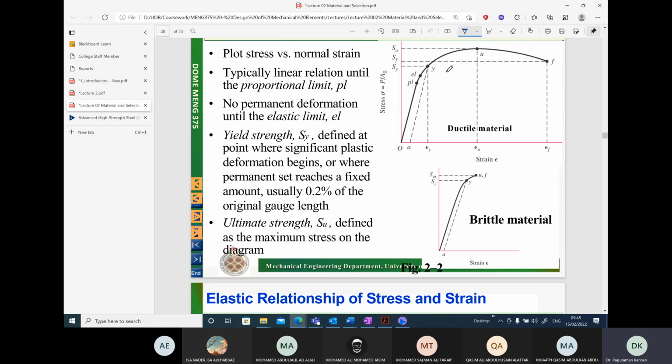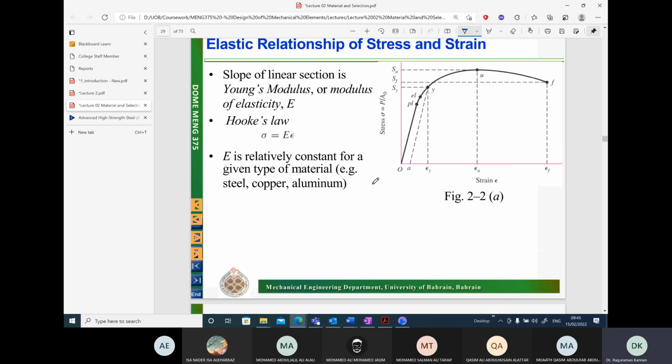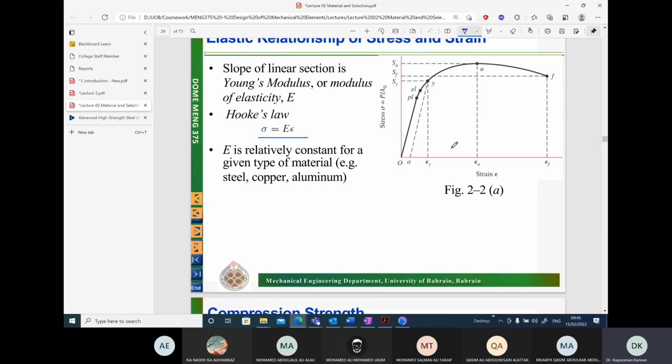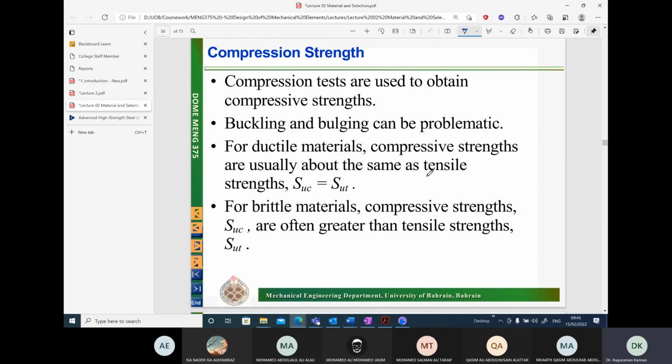Okay. So for ductile material, we have seen it has a huge plastic region. On the other hand, brittle material does not have any plastic deformation. In fact, you will see that if you draw to scale, the yield point and the ultimate fracture point are extremely close to each other in the case of brittle materials. For aluminum, we have already seen, we draw a parallel line at 0.2% and then figure out what the yield point is. This is according to the standards. So we have gone through this, and Hooke's law, we have already expressed that.